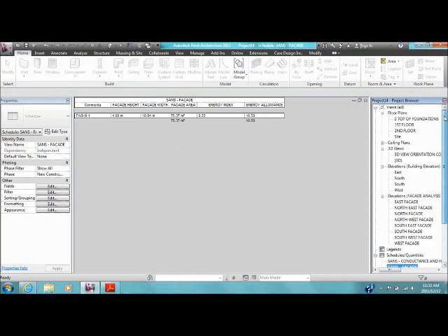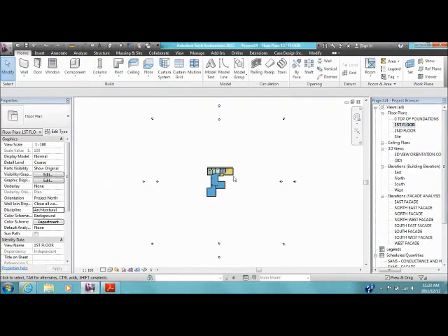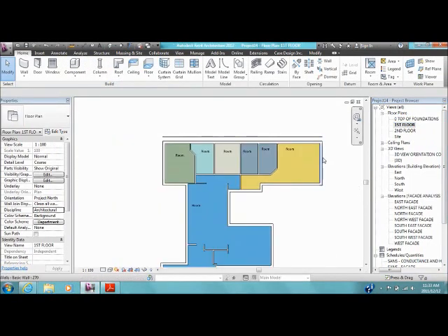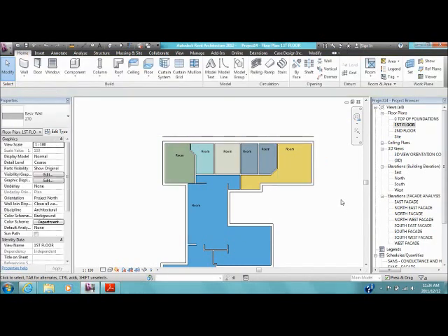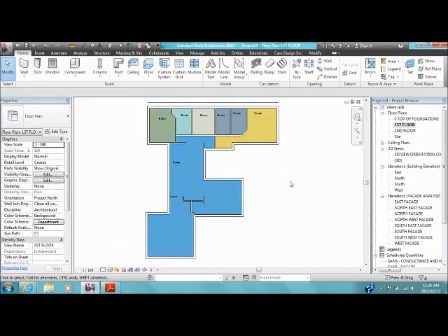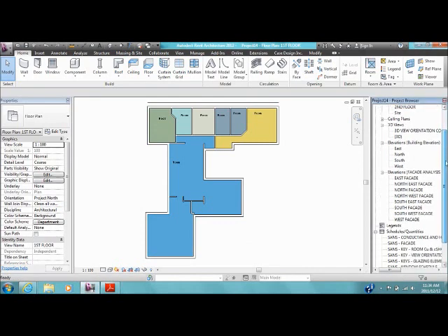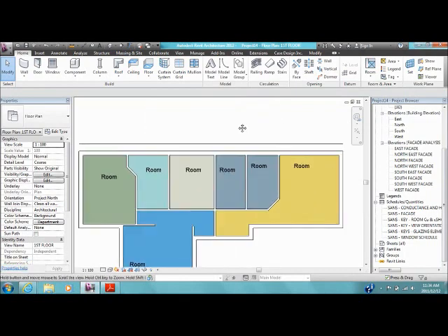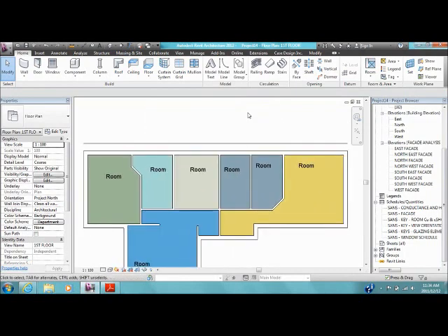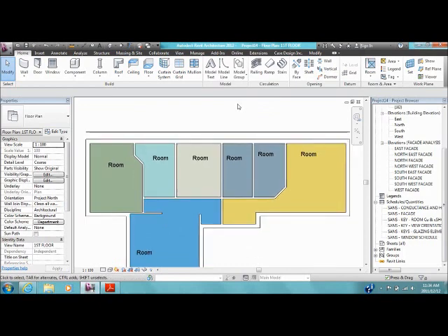The advantage once again of doing this inside of the Revit model is that if at any stage my facade changes, so this becomes shorter, notice how my gizmo changed as well because it was locked to the extents of the building. So no need to manually update any of the info that sits inside of your model. The next step would be to start placing doors and windows and then actually see what my energy usage is going to be based upon my fenestration.